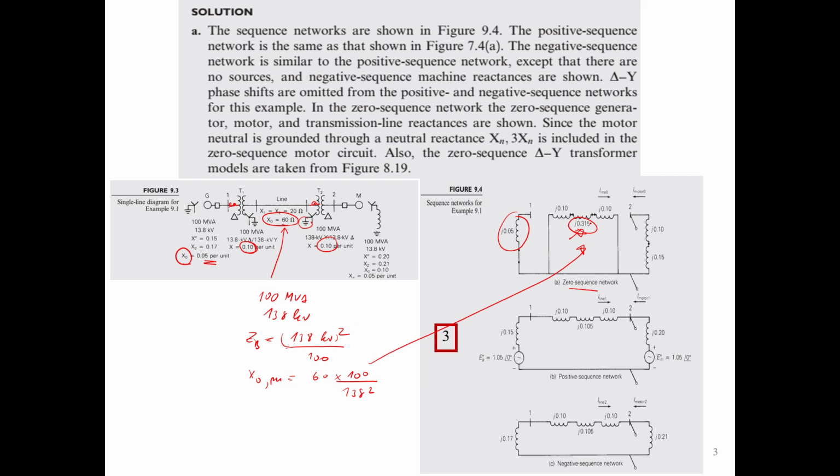Okay, now we don't need to do anything, right? To the motor, at this number 2, it is solidly grounded, and this case is delta. When there is a delta, these two are not connected. I mean, from this side of the transformer to the right side, the delta side, is not connected. So there is no path for the neutral current to flow, right?